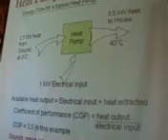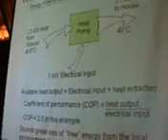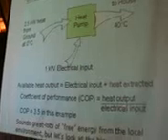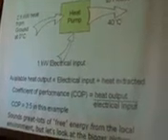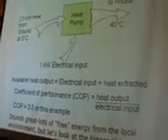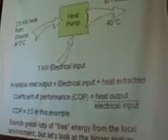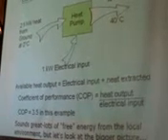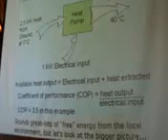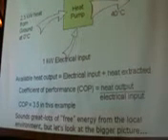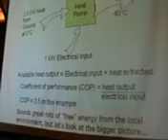And there's a thing called the coefficient of performance, which is the heat output, which includes the electrical input, divided by the electrical input. And that's the important sort of parameter, really. That's how much extra you get out compared to what you put in. Okay? In this case, that's a COP of about 3.5.